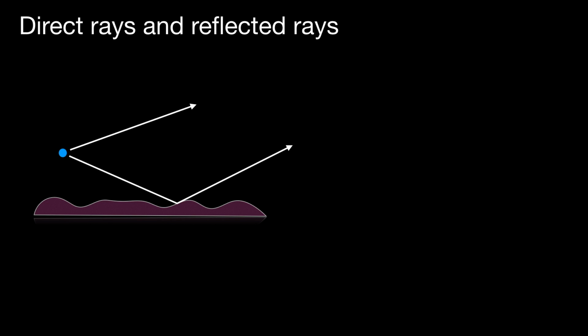Finally, we have a small discussion here, and again, I think we'll talk about this more in the propagation video, which I'll produce in due course, but direct and reflected waves. So there you see the end of a half-wave dipole and the incident ray going off into the sky, but also a ray going down to the ground and then being reflected off. And these two rays will combine either in phase or antiphase, or sometimes variably, for example, with the rising and falling of tide, to either augment or decrease the signal at the receiving end.